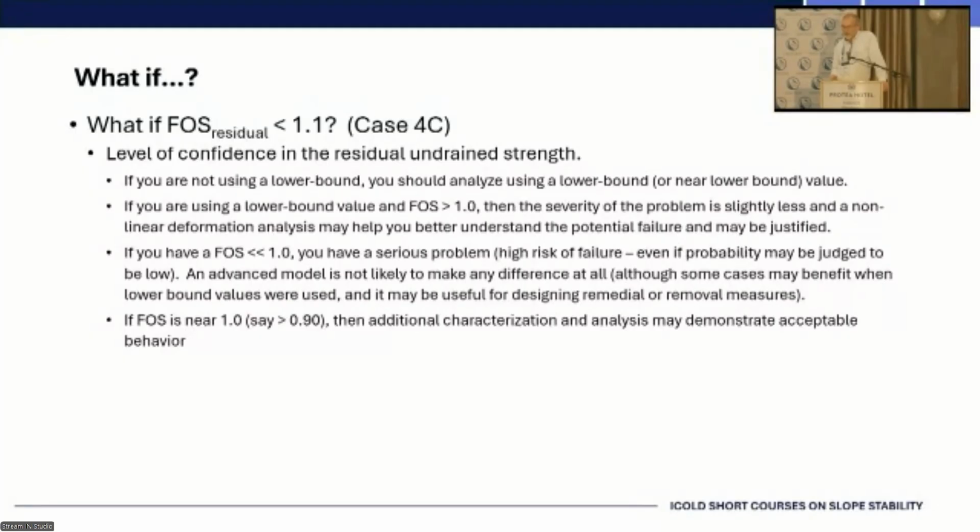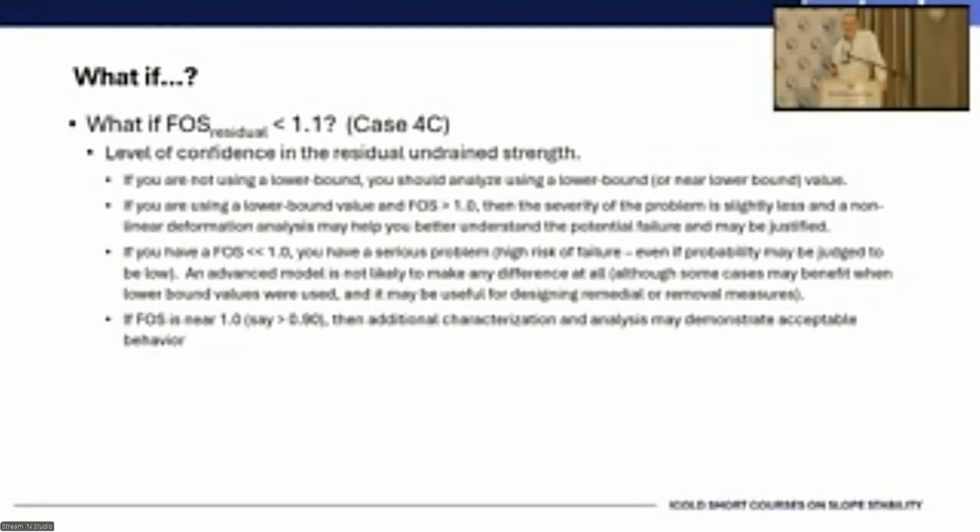If you are significantly less than 1 and you have a potential loss of life downstream, that's the hardest one to solve. There's no prescriptive answer. It probably means that you still need to do some more work, because you'd need to understand the vulnerability, which is the likelihood of a trigger occurring. So you'd want to evaluate the types of loading that could cause this.